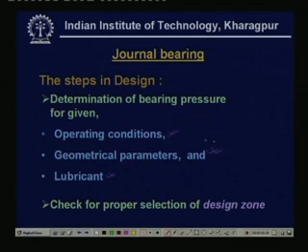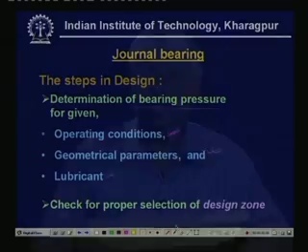These are the basic three things we will be finding out in the journal bearing design, and once we can finalize these parameters, then we get a bearing pressure. Once we find out this bearing pressure, then we know what will be the load carrying capacity.